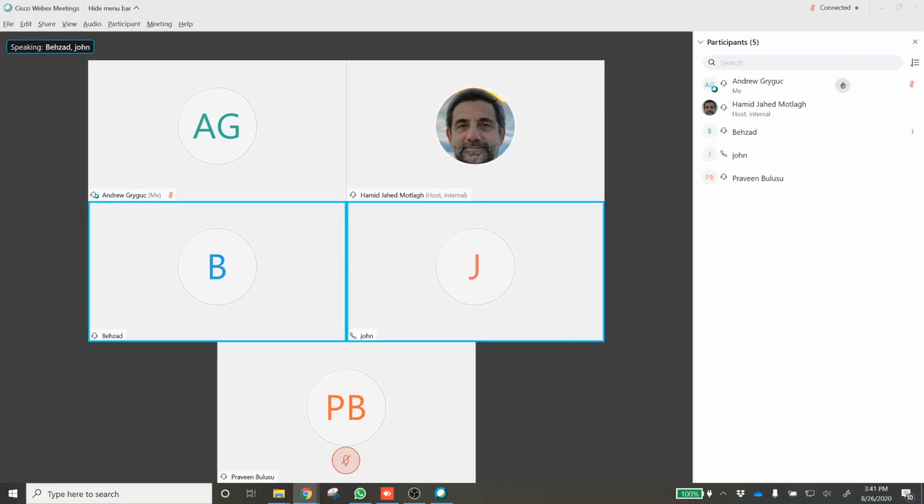The plan for testing the bolts, just to confirm, is to do static testing on non-hardened and case-hardened samples, maybe 5 of each, and then 3 of each is fine. You typically do 3, right? 3 of each is fine for the static strength. And then for the rest, whatever standard you follow is fine. Whatever number of tests you have been doing for all the other things is fine. Okay, you need a full strain life curve. Correct, for the case hardened one.